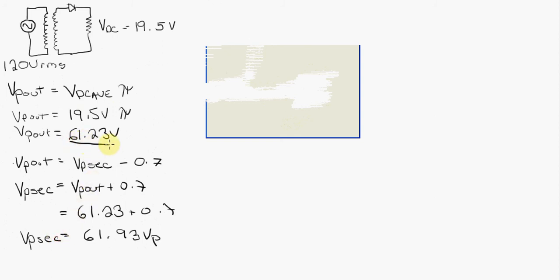So we now have the output voltage, and we now have the peak secondary voltage. Again, V peak primary, remember, was 120 RMS, which is 169.7. Oh, see there? That's some good work, eh? As I told you, if you're paying attention in earlier classes, 169.7 is primary.